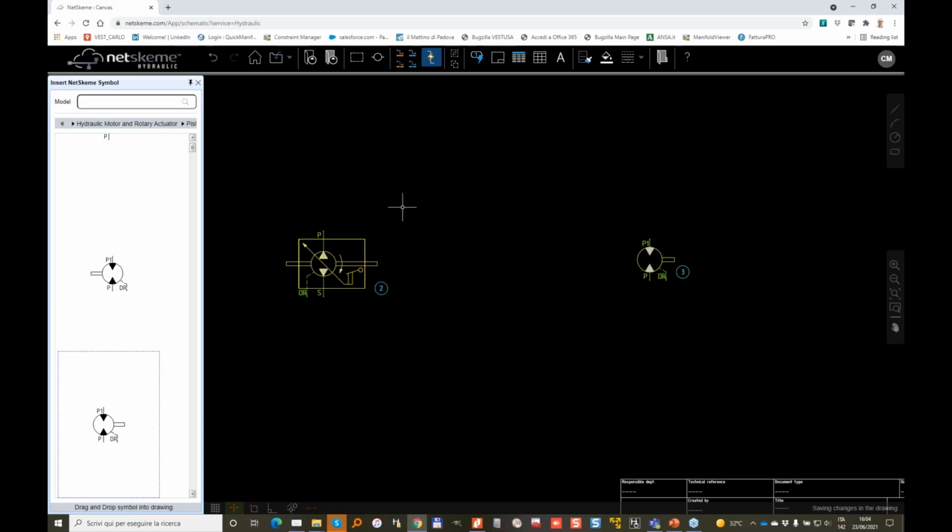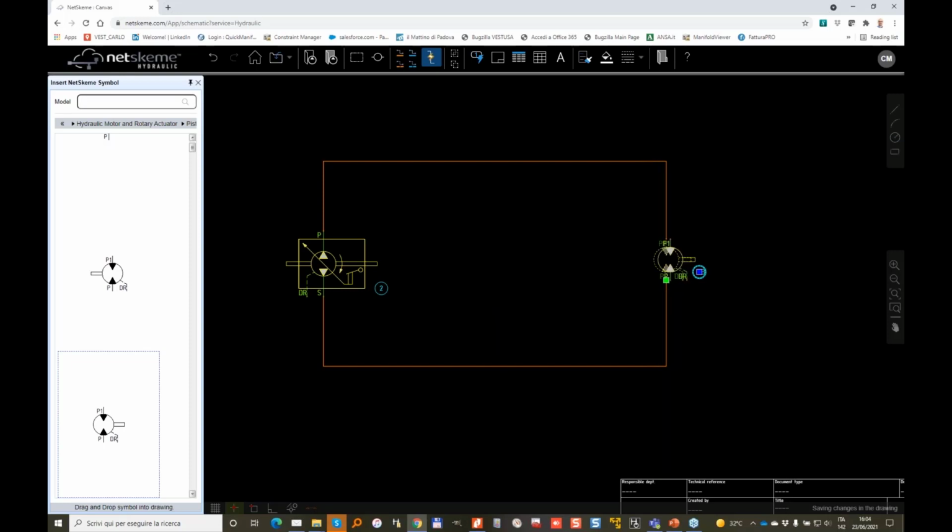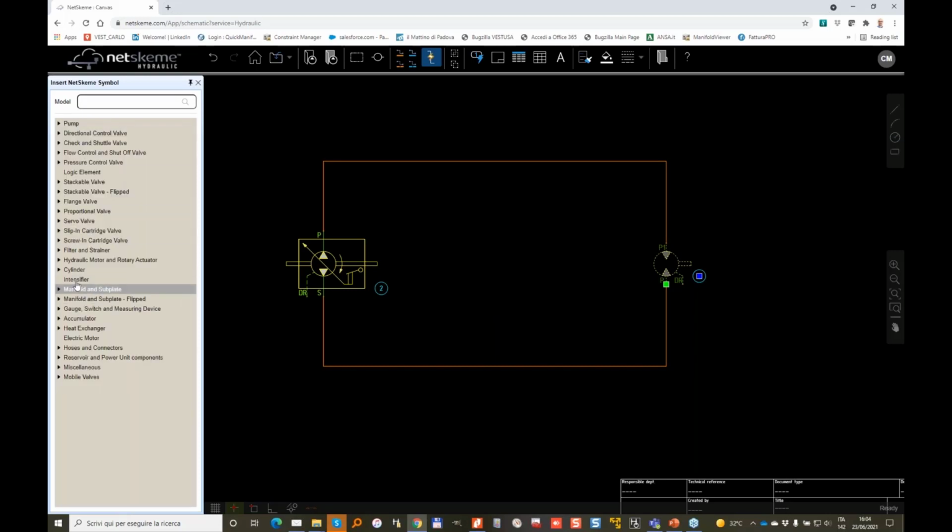Normally here we have a direct connection from the pump to the 2 sides of the motor, so we just make 2 connections. I'll make some movement, so I will just move this connection up and down. You just select it. If you move the symbol with the keyboard, then the symbol will move and the connection will update accordingly. Let's look for an electric motor.